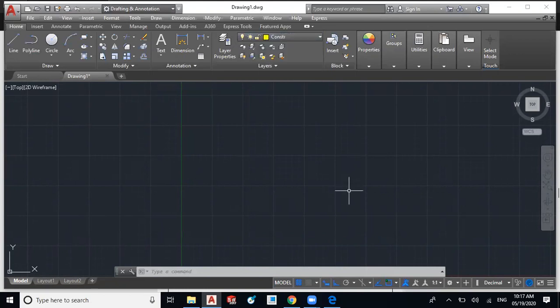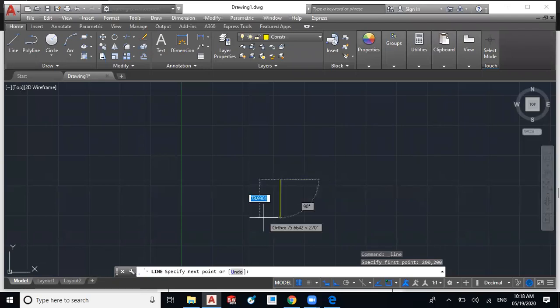Before starting, we have to draw the x and y axis, and then construct the spacing lines which we used in orthographic projections. So I have selected the construction layer, then I will select the line command. Now we have to use the coordinates of the center point of the working area, whatever we have specified. I have specified 400 as a working area, so I will select the center point as 200, tab 200, and then press enter. Then your line will start from the center point of your working area, and then we have to draw the line vertically downward.